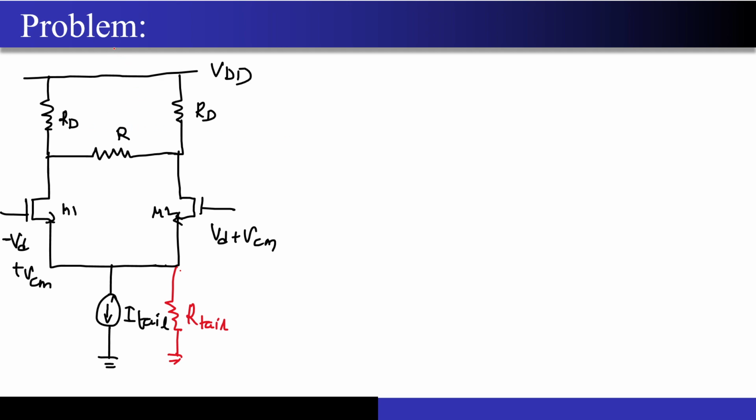Correct? Now can anyone tell me, if I wanted to draw a line of symmetry along this particular axis and I am facing a problem with this resistor, what should I do with this resistor over here? Can I do something with this so that I can draw a half circuit? 2R, if I do 2R and 2R, this will become 4R, right? 2R by 2 to ground. Yes, correct. So R by 2, then R by 2, in series, correct? So along the line of symmetry, this will be grounded. So this is what this person was saying, excellent.